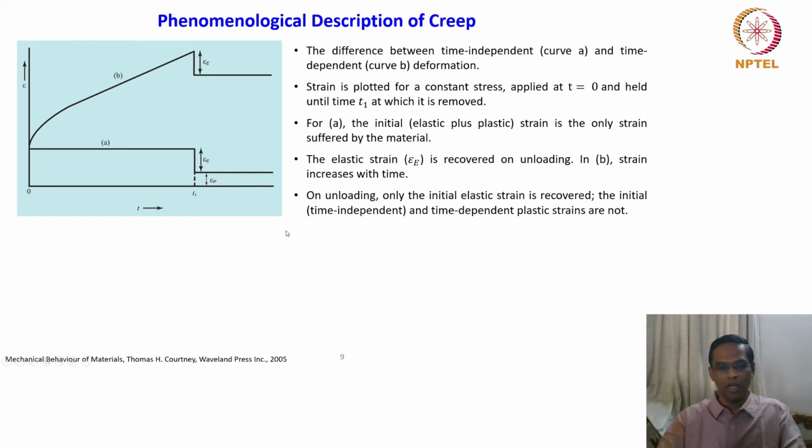This is a very important point. That's why the whole plot is brought here. The initial time independent strain is brought back, and the time dependent plastic strains are not recoverable. So the time dependent elastic strain you can recover, and the time dependent plastic strain cannot be recovered. That's the idea.